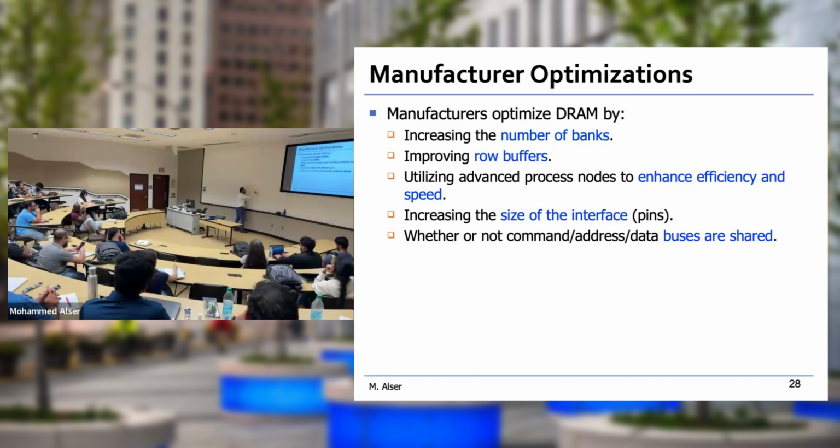So you start from the first DIMM, the clock cycle, right? You send a request from the memory controller. Maybe you get the data at some point here because there's always latency to service your request. Now, within that time, after you get the data, you need to precharge, right? You need to refresh that row because you already perturbed the row itself. You already altered the data itself. So while waiting for those housekeeping tasks, you can send another request to the other DIMM.